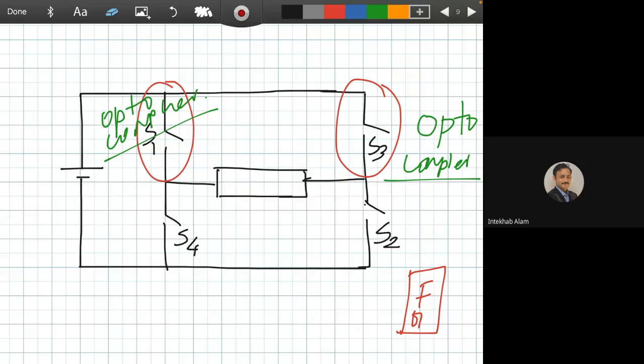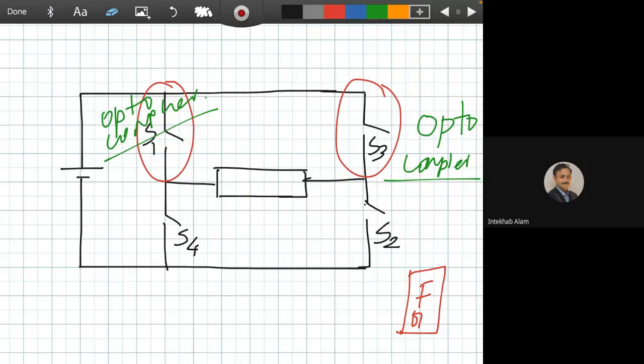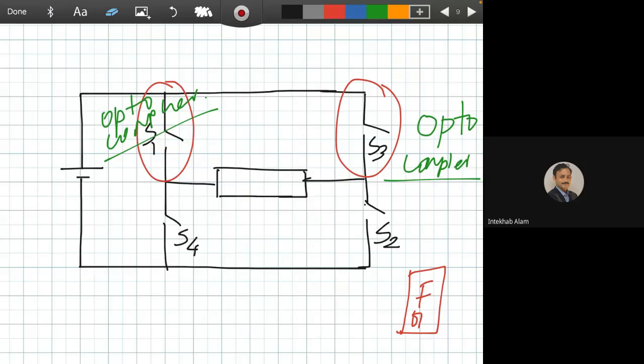If we start from the very beginning of this inverter circuit, we have studied single phase inverters with three topologies. One is push pull, the other is half bridge, and the last one is full bridge. In the push pull circuit, we have to use a center tapped transformer. There is a loss in the transformer, and the transformer is bulky, but the design is very simple. Hence, the push pull is a very inexpensive inverter.